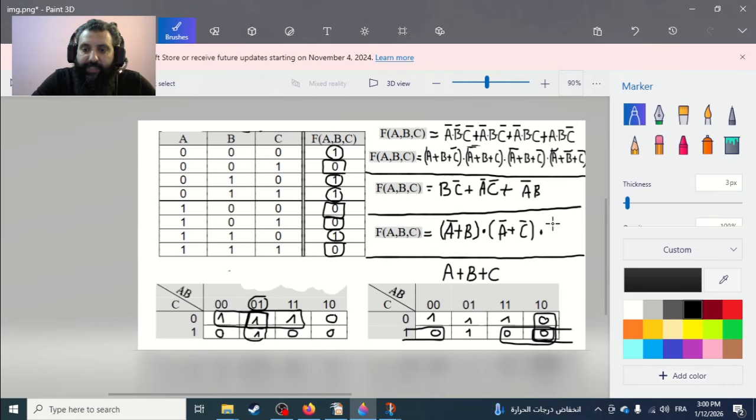Okay, and the last one is this one. If we look at the columns, we have 2 values on this box. We can tell that A is changing. A here has the value 0, and here the value 1. What's left is B. B is 0. I don't have to put a bar here, and A is eliminated.